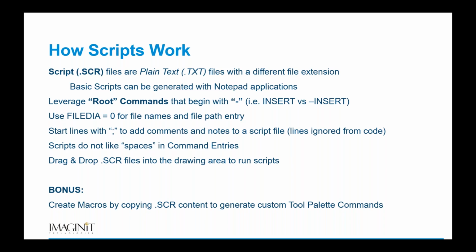I did mention scripts don't like spaces in command entries. So if you've got things like file names, when we look at one of the more advanced scripts that I have for page setups and so forth, plot styles and plot configuration files that have spaces, I ended up having to create a copy of that with underscores in them instead of the spaces. It was just something that the script file did not like. So I would do the underscores and try to avoid spaces in things like PC3 files and plotter configuration files.